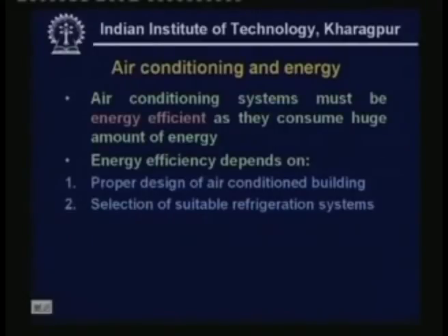All refrigerant systems are not equally good for all applications. So depending upon your requirement, you have to select a suitable refrigerant system. For example, in areas where a lot of waste heat is available, it makes sense to select a vapor absorption system, which uses the waste heat and not electrical energy or mechanical energy. So depending upon the situation, you have to select the required refrigeration system.